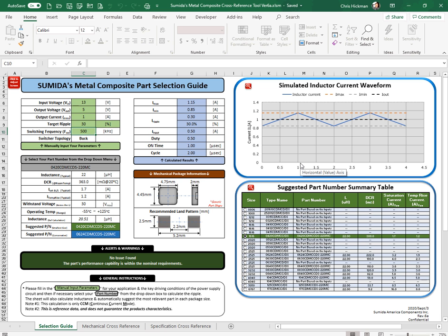While we are focusing on this section, let's try to get familiar with the calculated results and their graphical representations in the chart. First is Imax. This represents the maximum current swing based on the circuit inputs. You can see this in the graphical representation on the chart to the right. The max current level is shown as the orange dotted line and the top peak of the waveform.